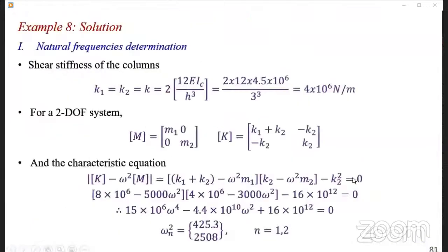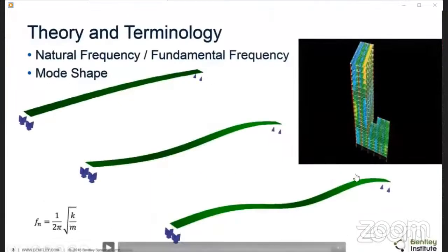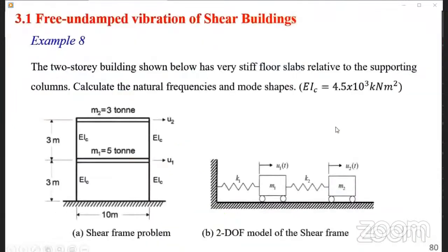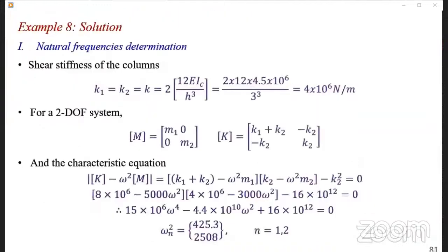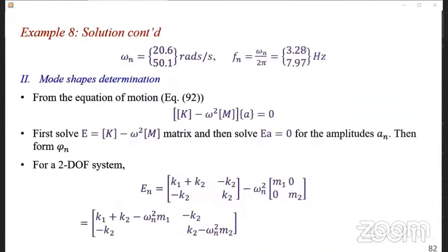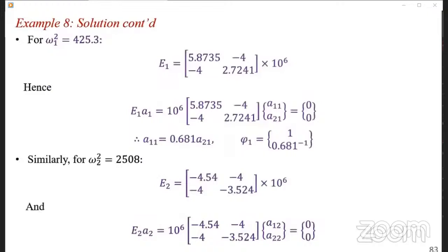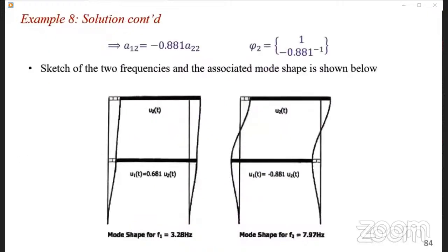So now, when we are solving this problem, if you recall, in brief, what he was saying is that every structure has got a tendency to vibrate. And the natural frequency at which they vibrate, of course, now that you're talking about solving the natural frequency, the structure will deform. For each vibration, it will have a different shape of deformation, what you call the mode shape. And we talked of mode shape being unitless. And we do this by normalizing.